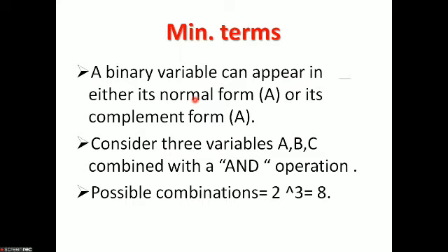Although a K-map can be used for problem solving for any number of variables, it becomes problematic for 5 or more variables. For doing the K-map, we need the min terms and also the max terms. Normally, we can do the K-map using the min terms only, that is the sum of product.